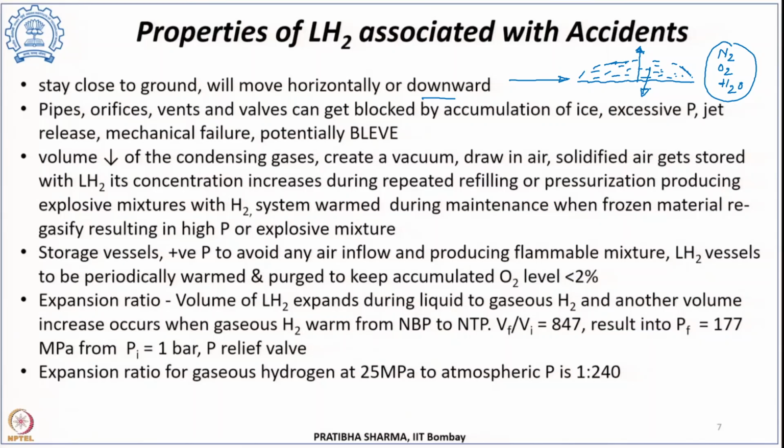Generally we want the buoyancy forces to act in the positive direction. If the buoyancy forces act in the positive direction, the hydrogen will move upward, and the accident risk will be less, because the removal of the hydrogen from the confined space will be easier, and there will be fewer chances of catastrophic failure. Okay, this is the thing.